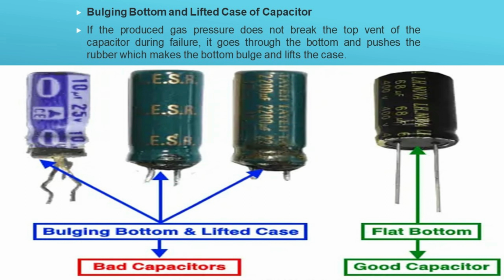Fully discharge the capacitor using a resistor. Rotate the knob and set the multimeter in continuity test mode. Make a contact of the positive, red, probe of the multimeter to the anode, plus, and common, black, probe to the cathode, terminal of the capacitor.